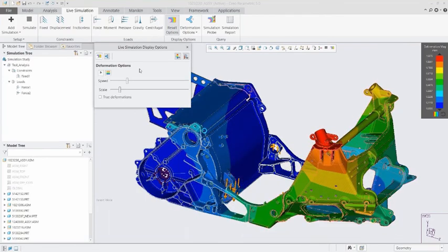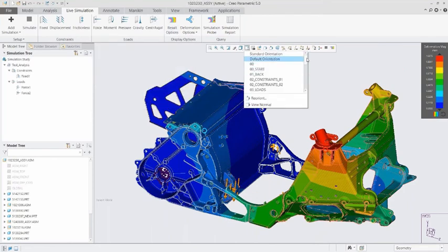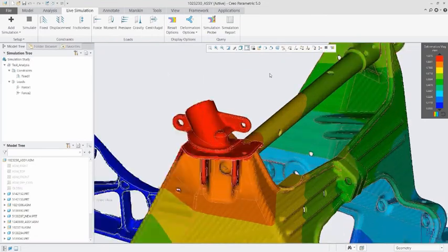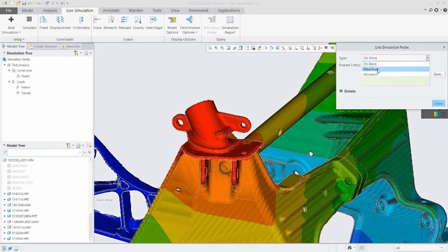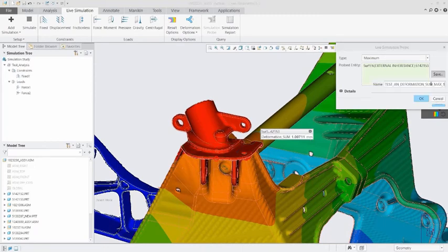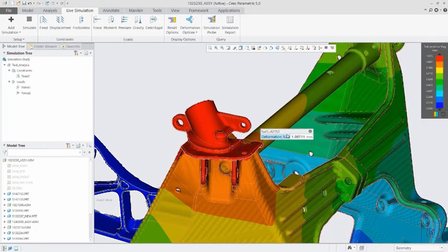So in my case here, with something like this chassis body, I'm worried about the deformation values that we're seeing. That gives us the ability to look at the areas we're concerned with and inquire on the values we need more information on. So here, of course, I'm looking at deformation. On this top face, we're getting around 1 millimeter of deformation.